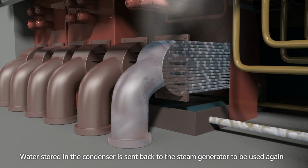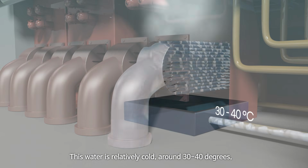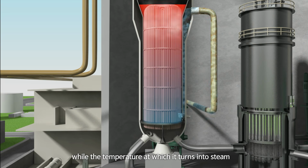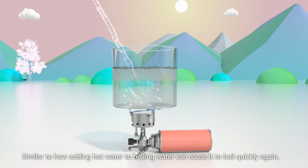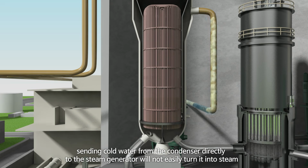Water stored in the condenser is sent back to the steam generator to be used again. The water is relatively cold, around 30 to 40 degrees, while the temperature at which it turns into steam in the steam generator is about 320 degrees, resulting in a significant temperature difference. Similar to how adding hot water to boiling water can cause it to boil quickly again, while adding cold water will make it harder to boil, sending cold water from the condenser directly to the steam generator will not easily turn it to steam.